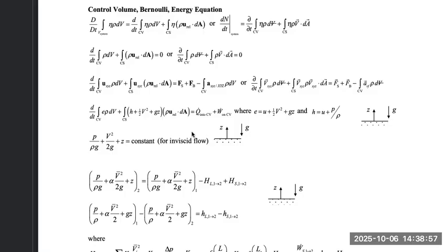Now let's look at the conservation of linear momentum equation that we will have to use, and that is this equation over here. This is the conservation of linear momentum equation. So sure enough, we see that it results in a net force. Fs are surface forces like shear forces and pressure forces, which is probably what we're interested in here since we're interested in the force exerted on the water by the wall, which will create a pressure, and also body forces like gravity.